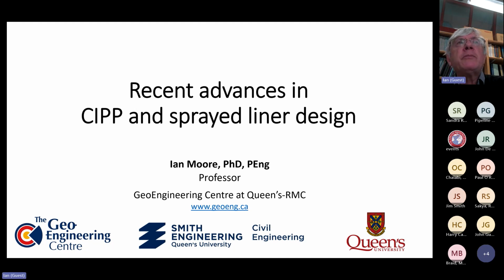That might be a reasonable approximation if you've got a light cured, ultraviolet or different wavelength of light cured, or photon cured, typically fiberglass CIPP liner system. They tend to have much less gap, or some of those products, it depends on the product, have less gap. And so the work that I've done to date is that conservative condition, or it will be conservative if you've got situations of initial gap.